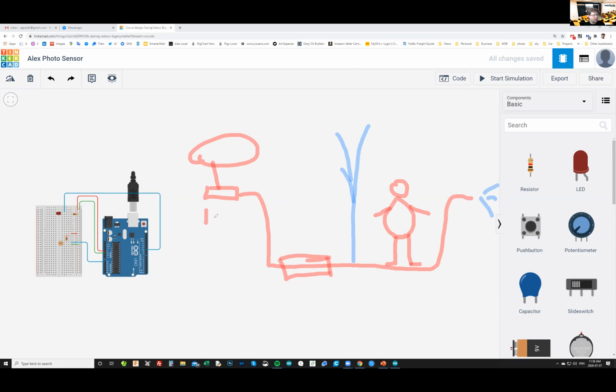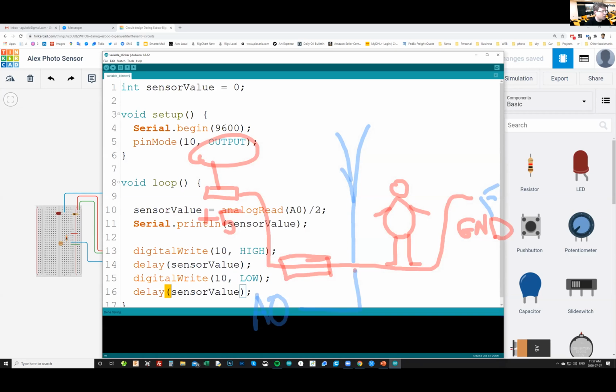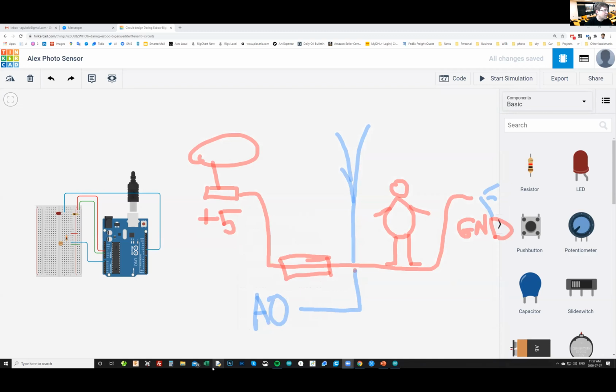I have plus 5 volts in here. And then I have ground in here because all the water spills out to the ground, right? Then I have a simple resistor, which is just a section of the hose. And here's a hole. And from that little hole, I'm connecting to my analog pin, A0, to read how much of that fountain is in the air. So the taller the fountain, I can say the darker it is, and the lower the fountain is, the brighter it is. You can calibrate your own circuit after, once you do the reading and put it in your serial monitor, you see that value. You can do adjustments, you can do math and things like that. So if, for example, I want to adjust my frequency of blinking, I can change my analog read and divide it by 2 or multiply it by 3 if I want to maximize the effect of that value. Do you get how it works?